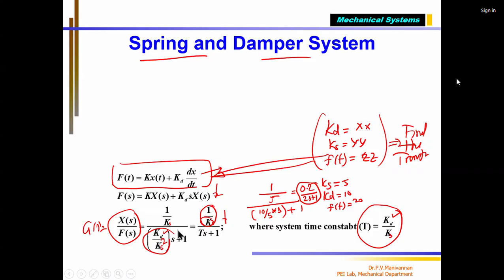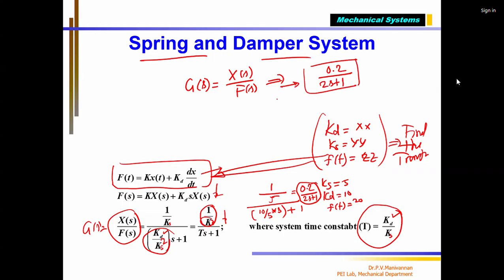Okay. Then we know that once you have the transfer function, what can you do? We know that the transfer function G of s equal to X of s divided by F of s. Now, the transfer function I already have. My transfer function for this system is given as 0.2 divided by 2s plus 1. This is my transfer function, for which I am giving input F of s. And I wanted to find out the...